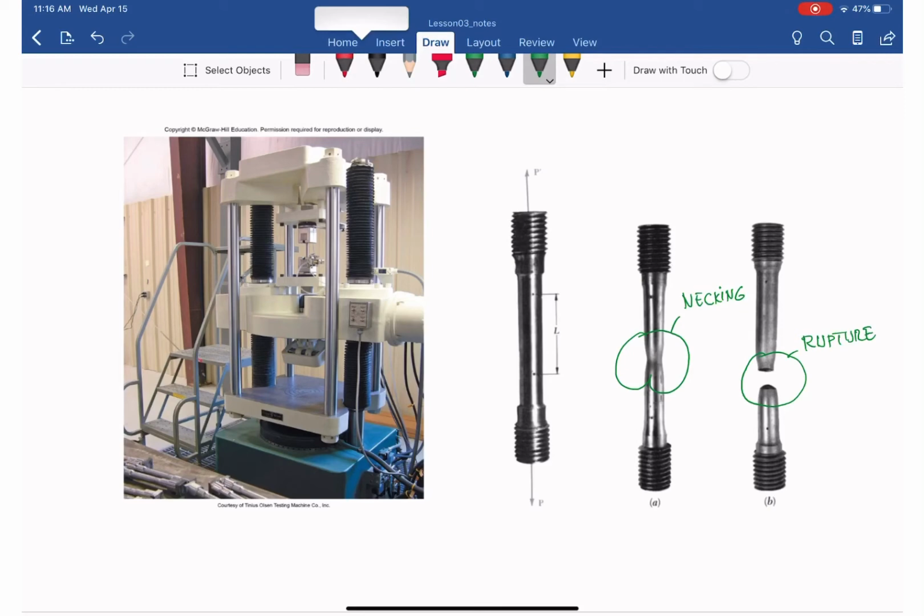That is rupture, necking. And the angle, when it ruptured, between the failure and the original form is about 45 degrees. And why 45 degrees? Because the failure in this case is normally the shear stress. And if you recall the worksheet 1F, when we vary theta from the transverse cut to any random cut from 0 degrees to 180 degrees, the maximum shear stress happens at theta equal to 45 degrees. So that is the necking in there.